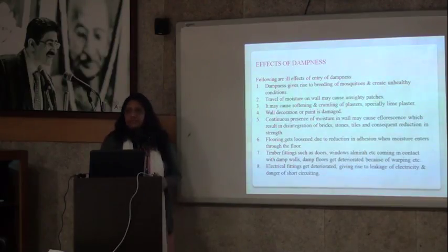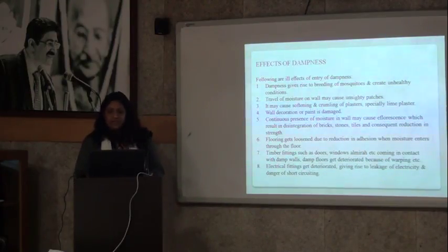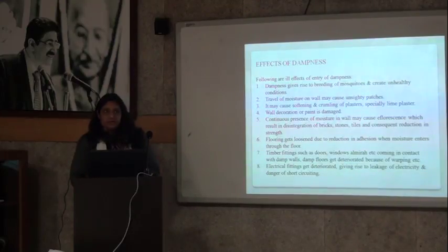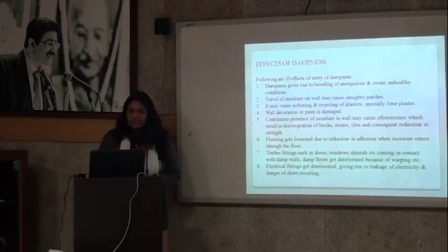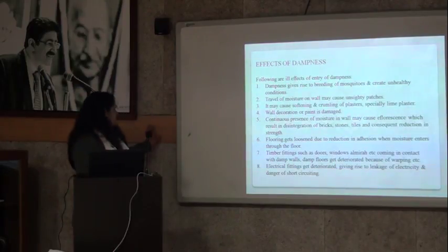So this way the floor will get very ill effect. Timber fittings such as doors, windows, almirahs, etc. coming in contact with damp walls and damp floors get deteriorated because of warping. Whatever woodwork we do in our space can even get affected with the dampness, as this wooden paneling